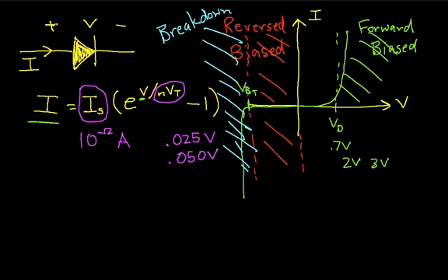There is a specific type of diode called a Zener diode that is designed to have a very specific reverse or breakdown threshold voltage, and is designed to operate in the breakdown region without any damage.